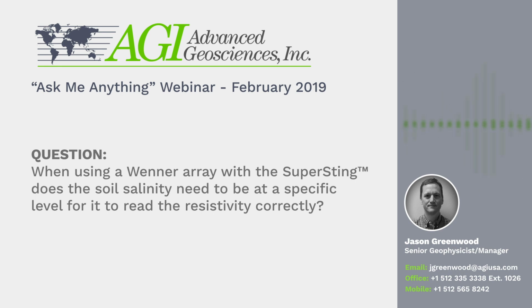But for 1D soundings and for grounding and lightning, like ASTM G57, it's the protocol for that, and especially the grounding engineers are concerned with resolving the average soil resistivity so they can design a grounding mat, the thickness of gravel, the step touch potential calculations and things of that nature. So I would say that anything from fully saturated soil with salt water up to incredibly resistive frozen soils is resolvable with the Wenner array.